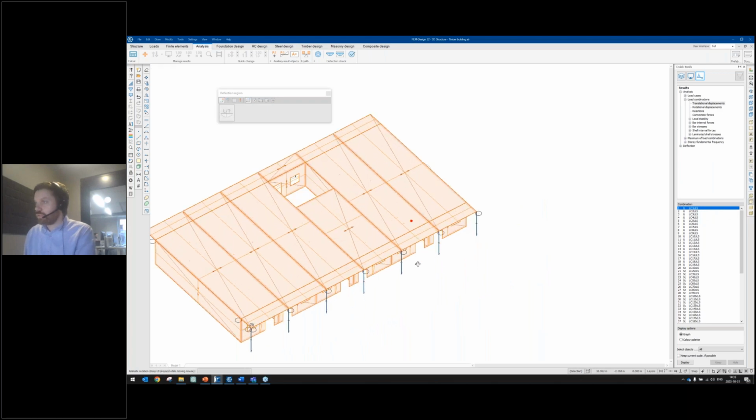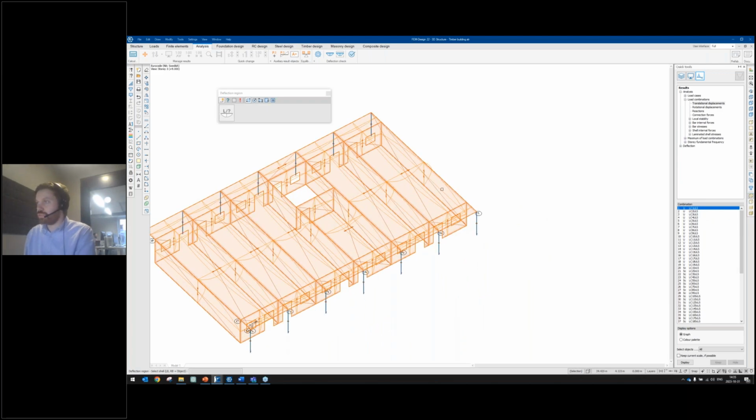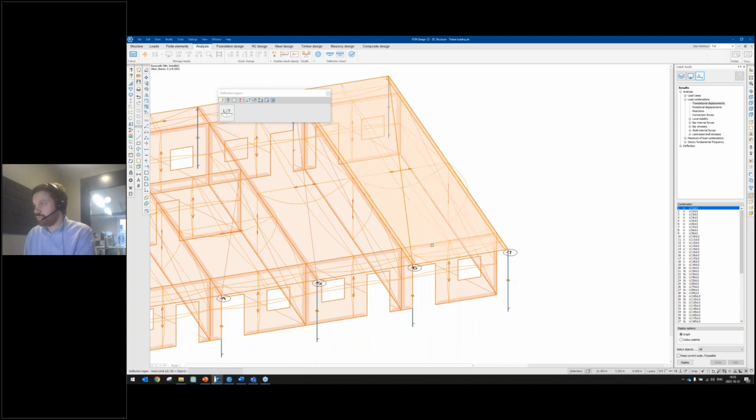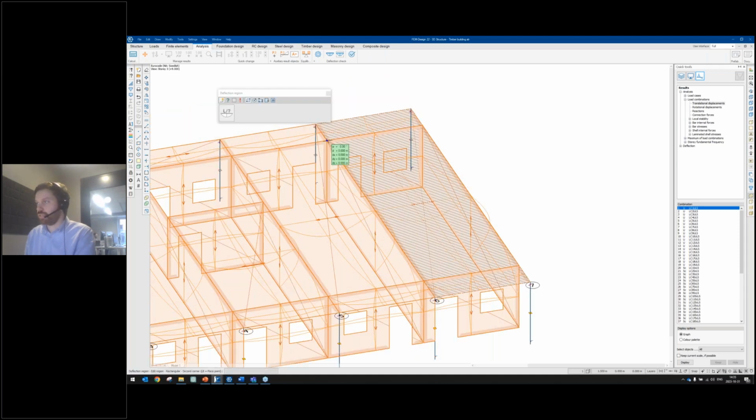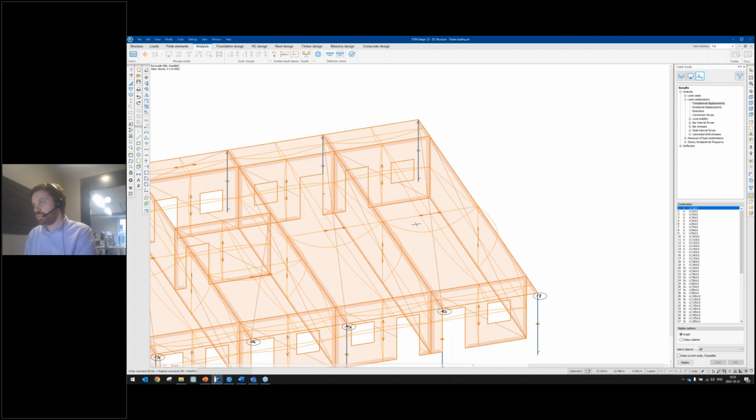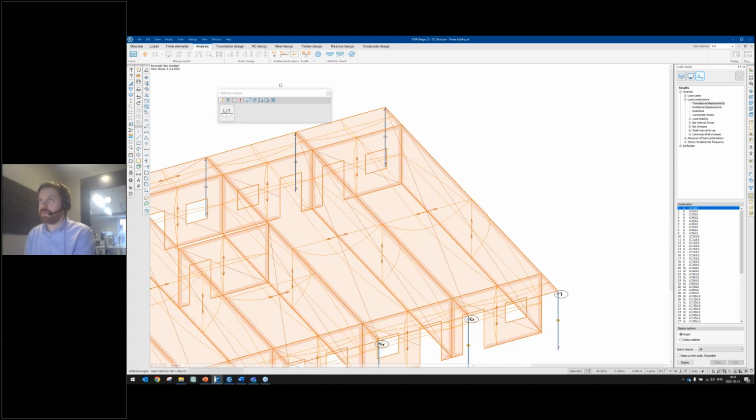Here we can see that the software has automatically divided this into different regions. You have 2 different arcs for each region, defining the short edge and the long edge. But you can divide this further into different parts using the pen, just selecting a shell and selecting a region. So let's say that I want to have this region instead. I can do it like this. But let's just undo that and go back.